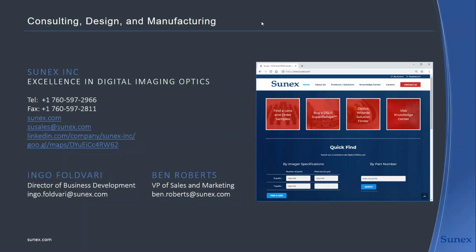What you also need to consider is, again, the total volume you may be looking at, because typically a molded lens, whether that is glass compression molded or injection molded plastic, spherical elements, they require tooling. So it's really important to understand the entire scope of the project, so that a higher upfront tooling cost can then easily amortize itself if you have a higher volume, because then the individual lens price is lower, because in the end, plastic is cheaper in the raw material than glass.